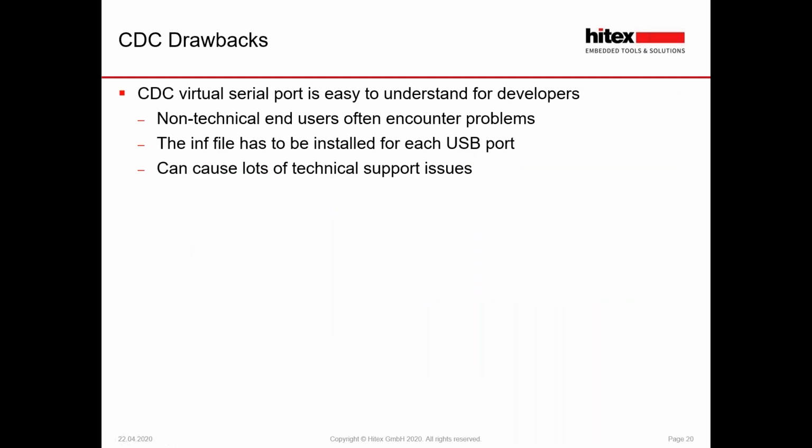One of the problems with virtual COM port is that while it generally works very well in the lab and for the developers using it, as soon as you let this out into the real world, it can become quite a problem. Users have to install the INF file. If it's a non-technical user, they can get confused.